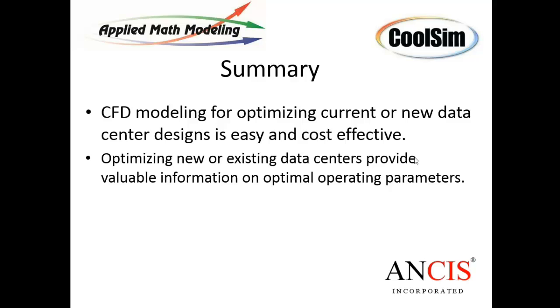Let's look at that. What's the best case condition? Let's look at that. Everything in between should be fine. And you are right, Greg, the data center is becoming a dynamic situation. It's becoming a transient situation. But you can still use CFD to get close to where you want to be, closer than you could without it. And you can study the corner cases, the extreme cases, very effectively to make sure your solution will work in those corner cases.